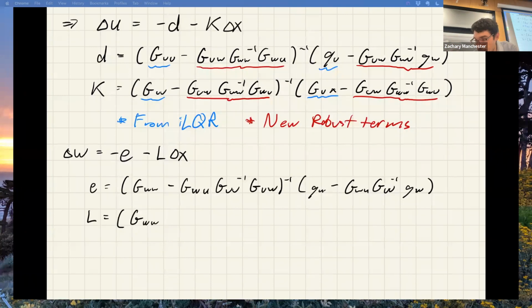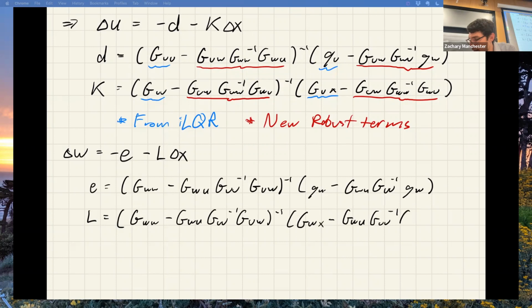That said, we're doing this sort of LQG-ish approximation of this thing where it's all quadratic. But I mentioned before, the maybe more correct way of getting at this is, rather than costs on W, to think about it as bounds on W. So this would really show up via constraints on W. You could put box constraints on W and say, okay, W can be anything in this range. There's no cost on it per se. That's more the flavor that is typical.